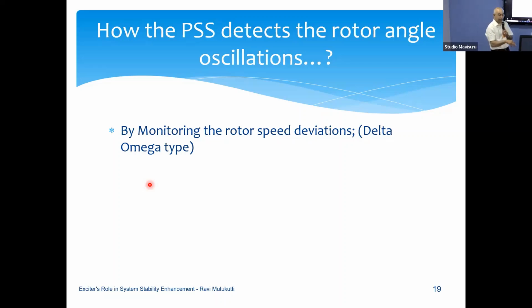But rotor instrumentation is very hard, because it needs to bring the signals back to the stationary world. Because it's rotating, you need slip rings. We tried instrumentation slip rings about 20 years ago, and it is a huge maintenance mess. You can buy instrumentation slip rings that you install on the rotor to bring the signals into the outside stator world, but it's very expensive, very maintenance intensive, and not worth it. So we abandoned that idea. So you don't have to try again, because you have examples that others have failed.